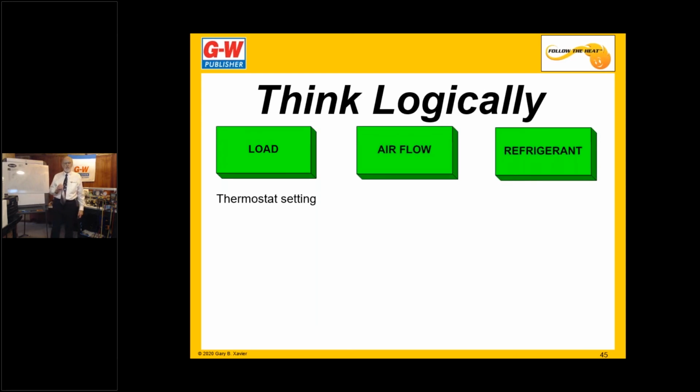we ice that evaporator. Have you ever noticed by looking at the pressure temperature chart that, for example, on R22, between a typically charged air conditioner and a frozen coil, there's only a 10 psi difference. And on R134A, there's only a 7-pound difference. It doesn't take much of a drop in pressure to ice that coil. So check the thermostat. That's number one.